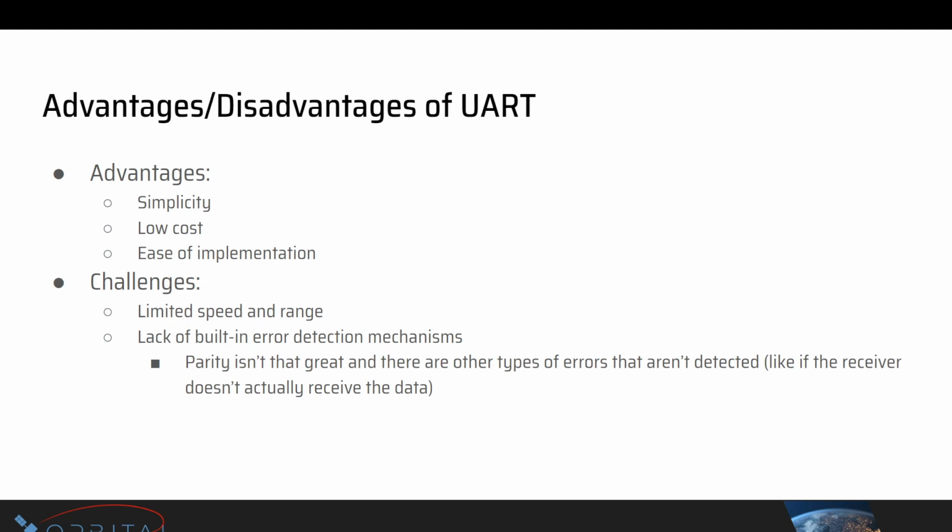So for the E people, you don't want to be making all your traces for UART and all your protocols super long, to the point where it exceeds the range they're good for, because then you're introducing extra noise and stuff, and the signals won't be as clean.